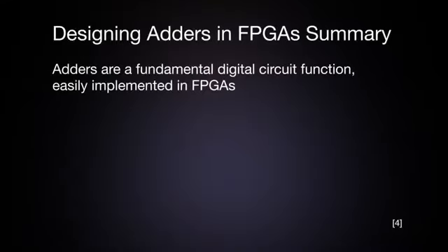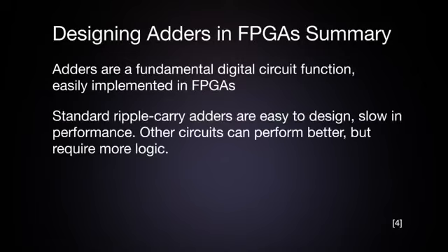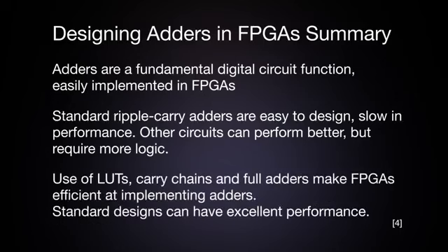In this video, we have learned adders are a fundamental digital circuit function that can easily be implemented in FPGAs. Standard ripple carry adder circuits are easy to design but slow in performance. Other circuit types can perform better but require more logic. The use of LUTs and additional arithmetic circuits like carry chains and full adders make FPGAs particularly efficient at implementing adders. Even standard designs can have excellent performance when implemented in an FPGA.